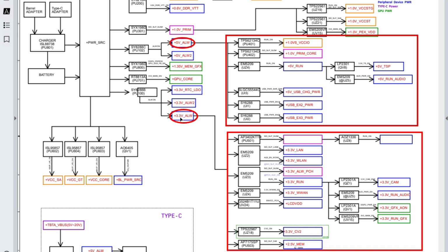That's why I focus on plus 3.3 volt and 5 volt, and of course I will make a lot of videos about these 2 voltages, because basically these 2 voltages are the motherboard. If you master these 2 voltages, that's it. You can repair any Mac. Sure, 100%.